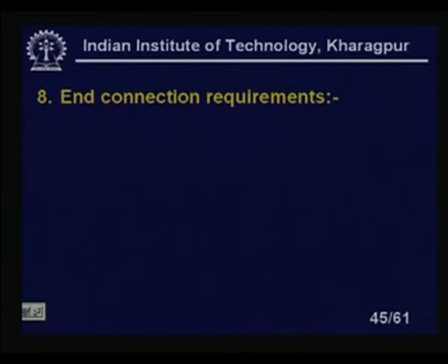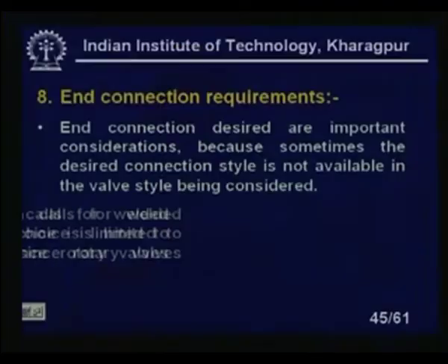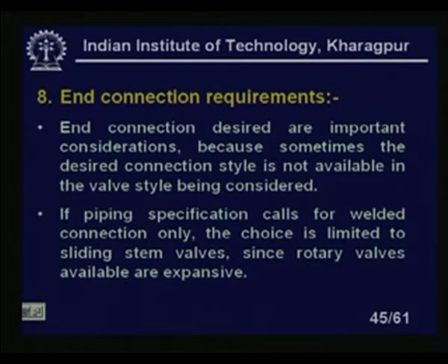End connection requirement, this is another important thing. The end connection desired is an important consideration, because sometimes the desired connection style is not available in the valve style being considered. What type of pipe you are installing, and what the end connection is, that means the inlet connection and the outlet connection to the pipe, is to be considered also. Not all types of end connections can be made on all valves. Accordingly, you have to choose the valve. If piping specifications call for welded connections only, the choice is limited to the sliding stem valves, since rotary valves available for that are expensive.